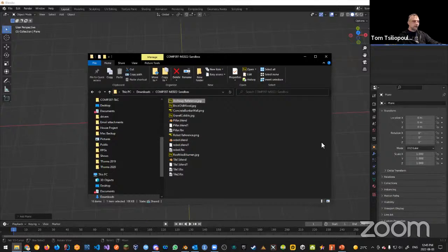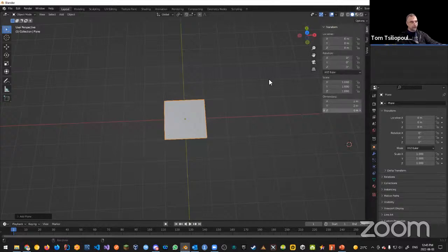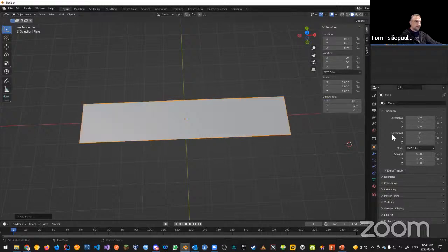Goodbye. And what I want to do now that I know it's 1,000 by 700, I estimated in my head 10 meters by 5, but it's actually 10 meters by 7 because that's more accurate. So if I want to make it 10 meters by 7, we can model it here by using our trusty numeric scale, by using the N key. The N key brings up our transform, right? And we can do it here.